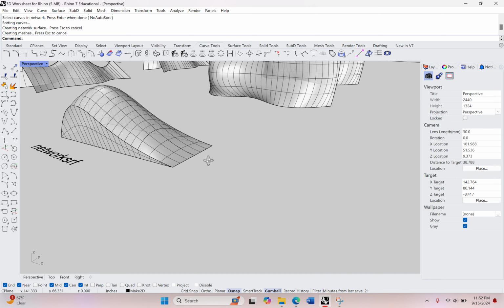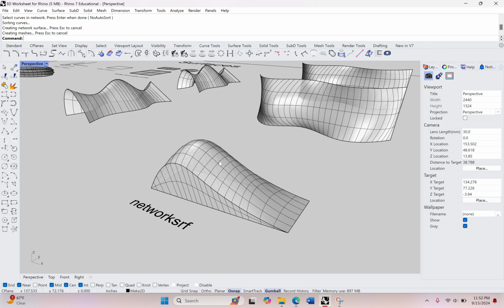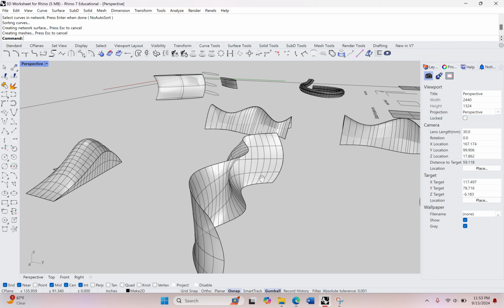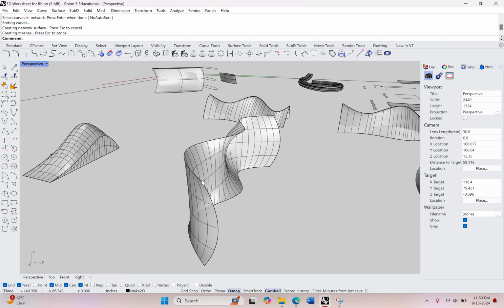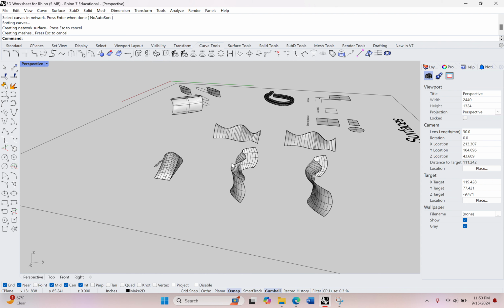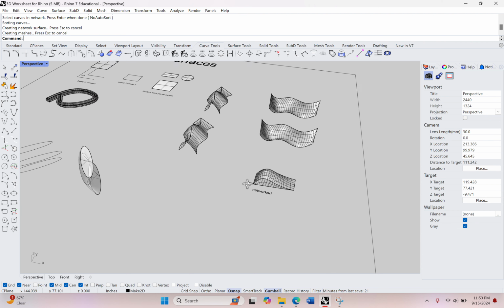If you had something similar and you wanted to seal it all the way up to make a mesh or a closed polysurface, that's simple enough. You'll just need to create additional geometry and start closing things up, either with surface from planar curves or sweep 1 or 2. Generally, those are fine. Or loft.